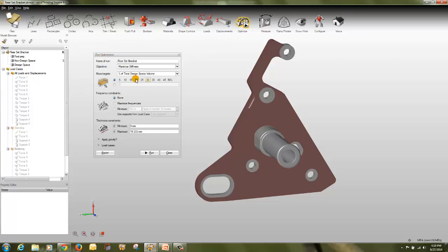Now I'll show you the run optimization tab, what is there. So we'll start with the name. First is the run name. You can put any run name, whatever you want. So run name: when you run an optimization, the name of the run defaults to the name of the part used as the part design space. However, you can assign your own name in the run optimization window.